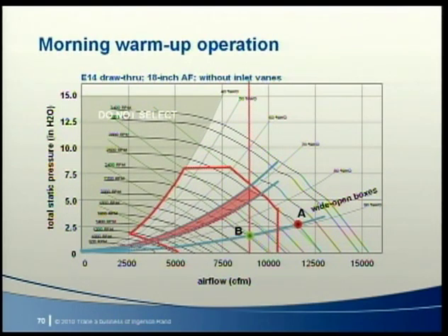A third approach forces the VAV boxes to a specific airflow, say 80% of design, rather than wide open. Duct pressure can be controlled and the fan speed would decrease to deliver an acceptable lower airflow. The bottom line: whatever approach you use to control the fan during morning warm-up, be sure that your fan selection